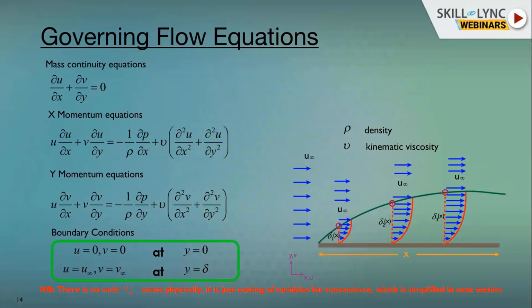These are very standard. This is my steady state Navier-Stokes equation. I have convective terms on the left side. I have a pressure gradient term on the right side, first term, the negative del P by del x term. Then these nu times terms are the diffusion terms. They represent my viscous dissipation, right? To solve this set of equations, we need a set of boundary conditions, right?